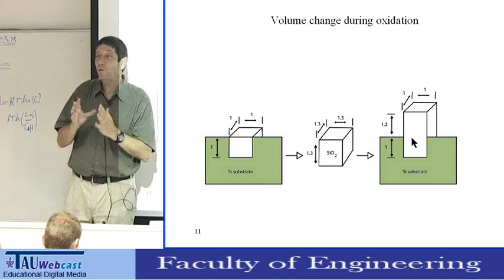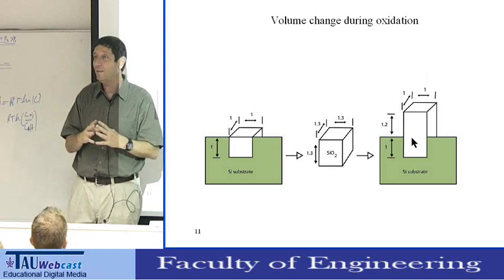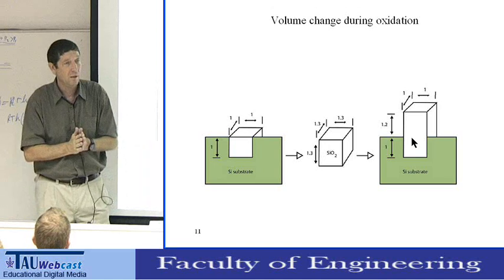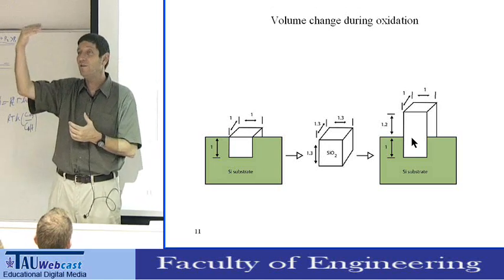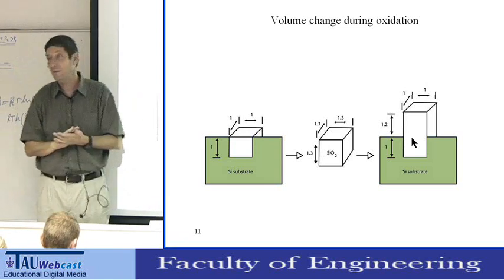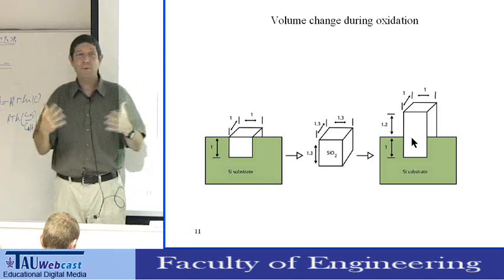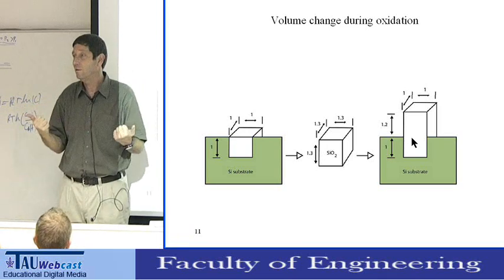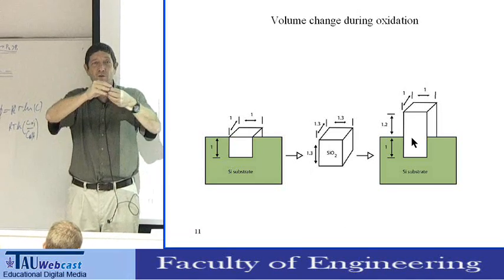This temperature of about 970, 980 degrees Celsius is the glass temperature of silicon dioxide. Above 970 or 980, the glass behaves like a viscoelastic material. Below, it behaves like an elastic material. And because it's elastic, it's like a spring. You push it, it pushes back. At high temperature, it's viscoelastic, so when you apply a force, it can flow.